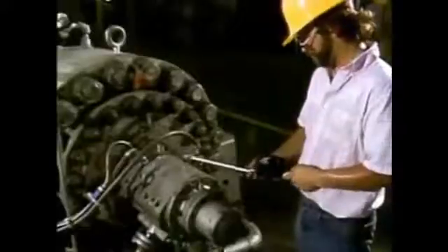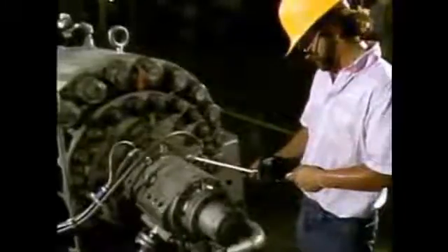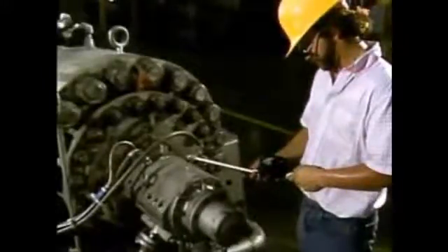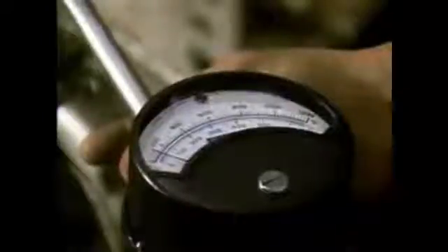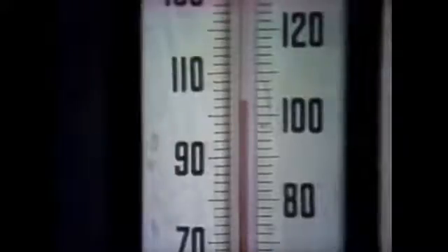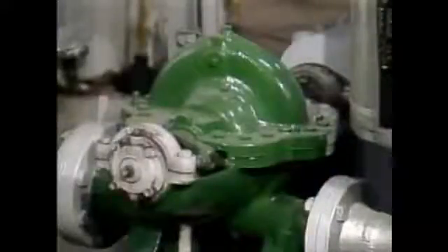When more precise temperature readings are required, it's usually necessary to use a temperature instrument, such as a pyrometer, to monitor equipment temperatures. In addition, some pumps have indicators for bearing and lube oil temperatures. An increase in temperature could mean there's a problem with the lube oil supply, which is causing the bearing to overheat. This pump is running normally.